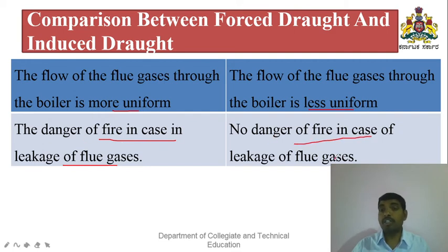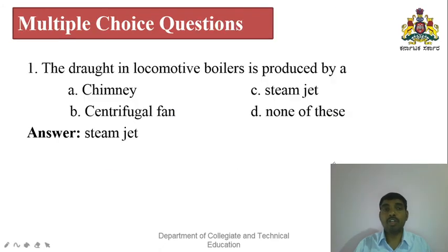There is no danger of fire in case of leakage of flue gas here. Here we are sucking in the cold air. For that purpose, no dangerous condition is possible in the path of the flue gases, or while moving the flue gases, there is no danger to expect from this induced draught. These are the comparisons between forced draught and induced draught.